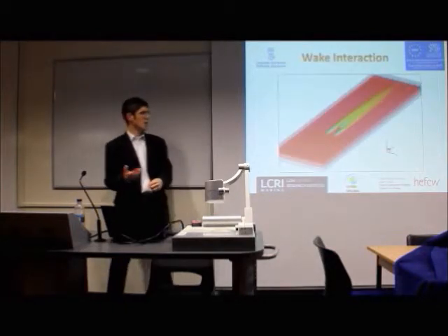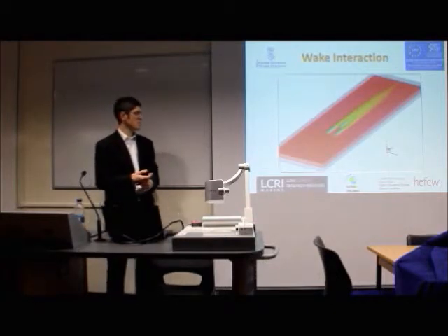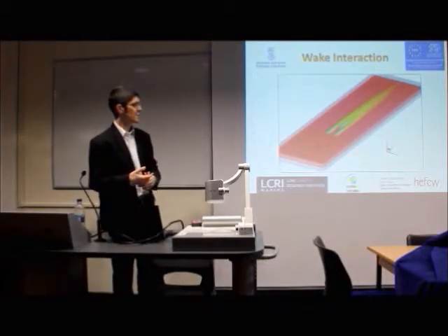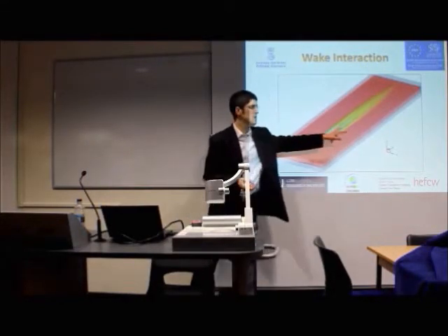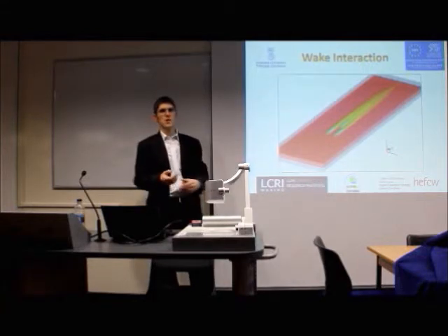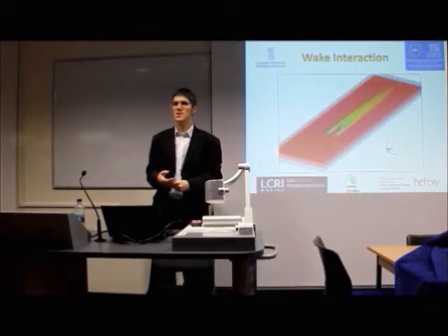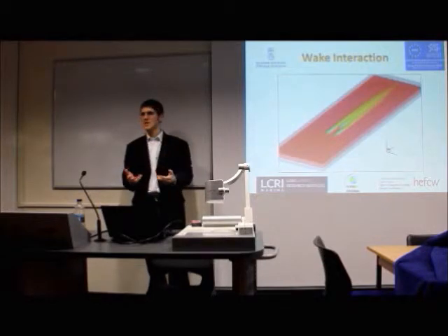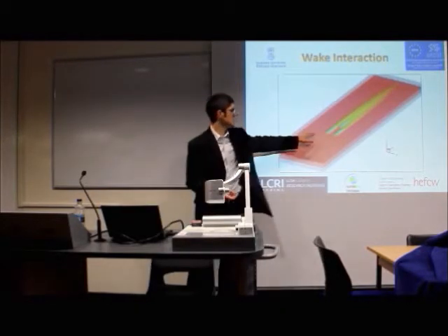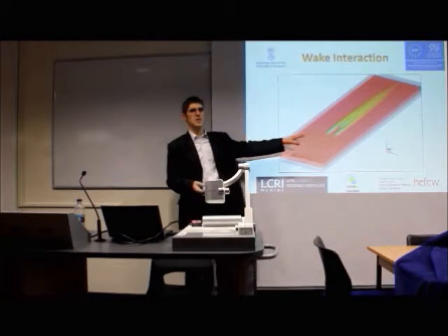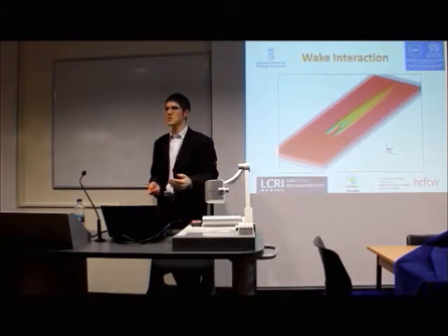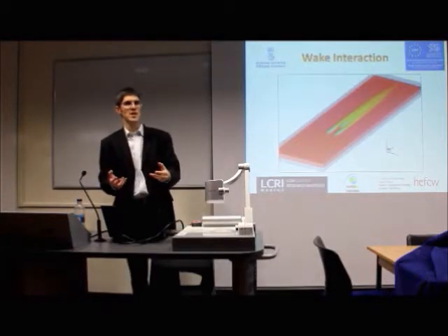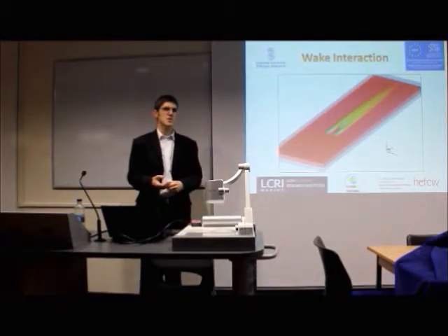If you can do that, lower levels of computational cost, you can afford to do models of quite big patches of water. If these rotors are 10 metres in diameter, and we've got 1, 2, 3 of them, that ends up a kilometre long flow model. So can we do that? Is that conceivable? And from 3 rotors, we're already talking about 10 megawatt farms, 20 megawatt, 30 megawatt farms. So you might be looking at 10, 20, 30 rotors. And that's a lot of compute power if you try and model that using this type of approach. So you need to find these intelligent ways of doing it.